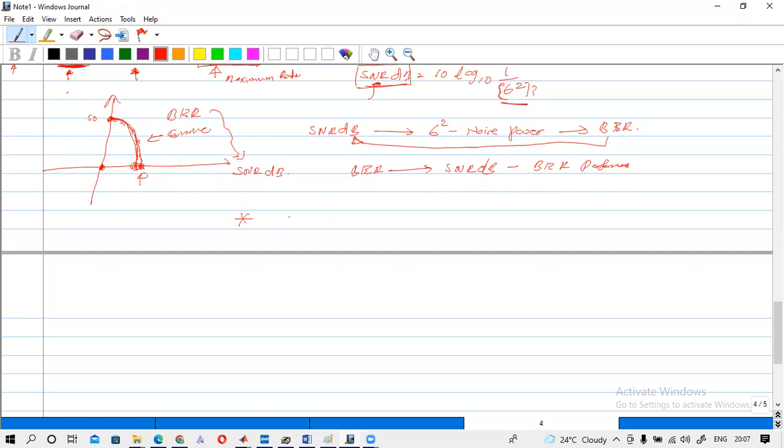So that is the idea. We have to get separate SNR dB values. So this SNR dB from 0 to 40, I think it is a good range, because if it is less than 0, there is no effect. The bit error rate will be very high. And at 30, 40, you will be having 0 bit error rate, because the bit error rate is very low in this range.